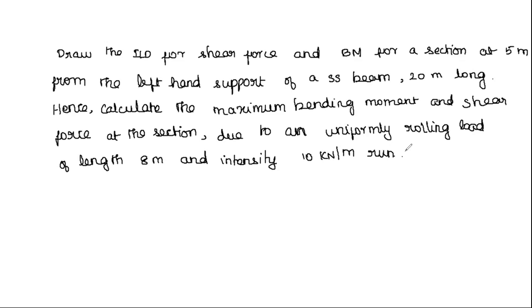So we have to find the shear force and bending moment at a section 5 meter from the left hand support of a simply supported beam which is 20 meter long, and we have to calculate the maximum bending moment and shear force at this section due to a uniformly rolling load of 8 meter length and intensity 10 kN per meter run.